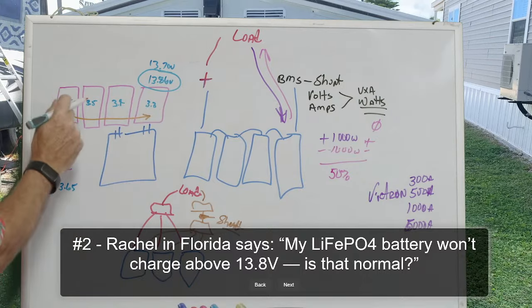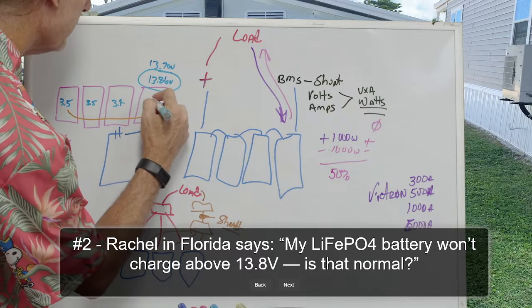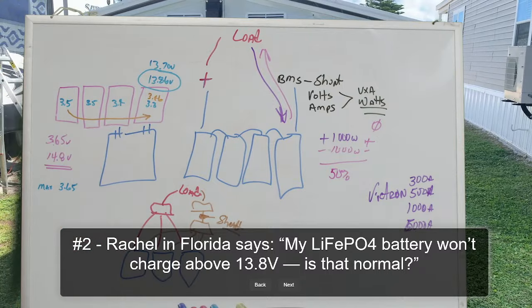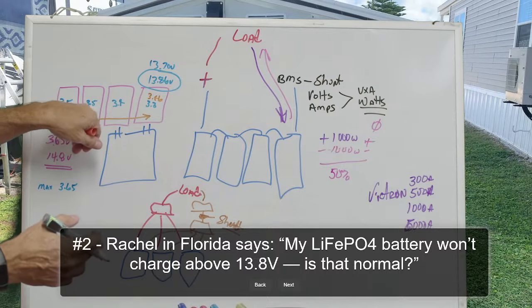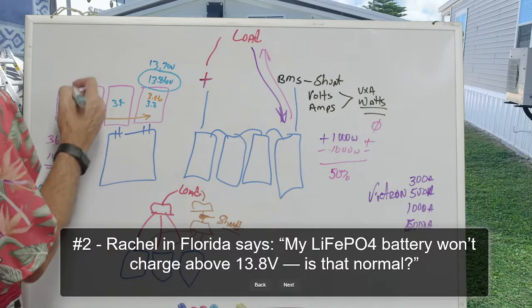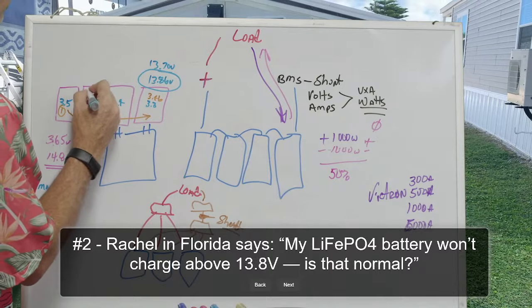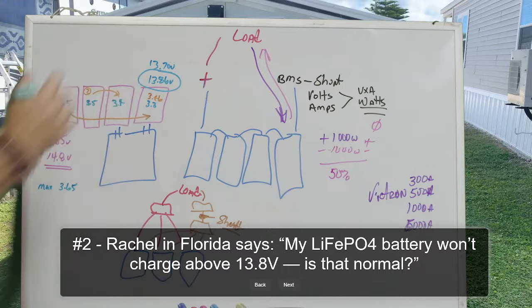And if it took that 0.16 out, it may put it over here, bringing this to 3.46. And thus, the next time it went into balancing mode, it would need to take from one of these to give to that one. And that would be the first step it would take. And the second step it would take would be to take from one of these cells and give to that cell. And that would allow it to balance.